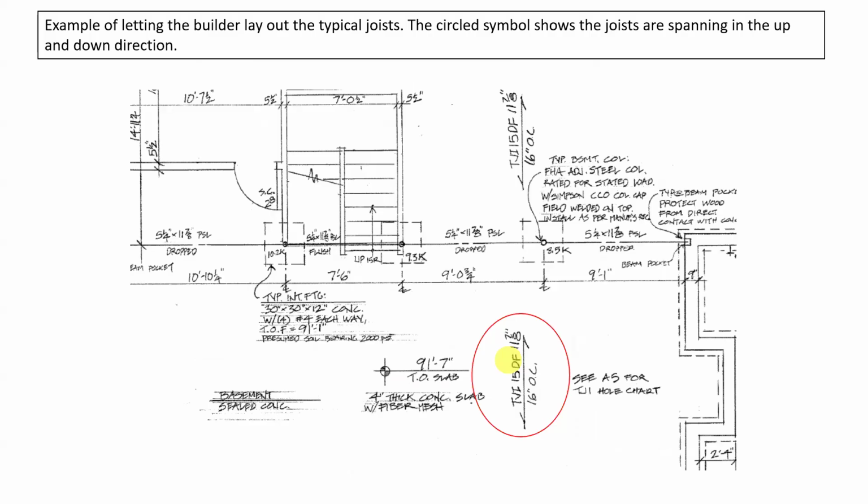So I talked about this before in the other class. I do want to give you guys a little quiz. So there's my floor joists, they're running up and down. There's my beams. I use parallel strand lumber, 5 1/4 by 11 7/8, and they're all 5 1/4 by 11 7/8. Some of them are dropped, and one of them is flush. Why did I make that one beam flush and the rest of them dropped? Because my dad's tall and I'm tall, and to maintain code required headroom, I couldn't do a drop beam because my dad and I would both be bonking our heads on it.